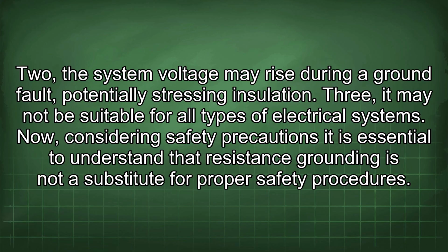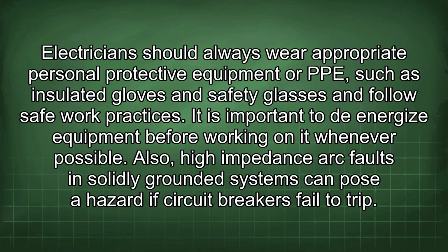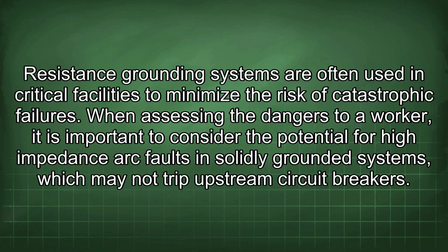Now, considering safety precautions, it is essential to understand that resistance grounding is not a substitute for proper safety procedures. The electrician should always wear appropriate personal protective equipment, or PPE, such as insulated gloves and safety glasses, and follow safe work practices. It is important to de-energize equipment before working on it whenever possible. Also, high impedance arc faults in solidly grounded systems can pose a hazard if circuit breakers fail to trip. Resistance grounding systems are often used in critical facilities to minimize the risk of catastrophic failures.